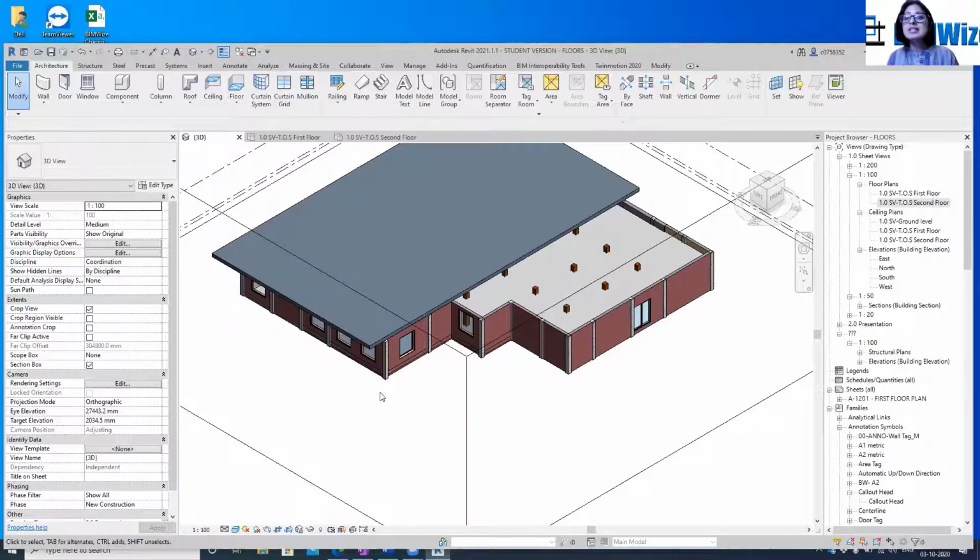Now what happens is Revit is a smart software. There is an intelligence built into it in which, tomorrow when you're creating a schedule out of it, and there would be some properties, you create a roof schedule. If you have created this as a floor, it would not even generate. So when you take material takeoffs, or when you are doing anything that's related to roofs, because you drew it as a floor, it will not even show up.